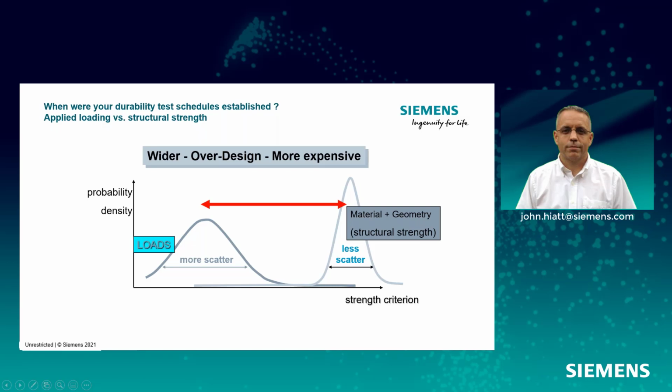Sometimes in the military, but over-designing, if you don't go with exotic materials, composites or space age materials, generally it takes mass, weight, thicker materials. And when you add weight, you have other attribute trade-offs. So military applications have to be careful. On a tank, if they add weight, they reduce the range, they reduce the speed of the tank. So there's a big trade-off. But oil and gas, it's basically keep it going, over-design it.